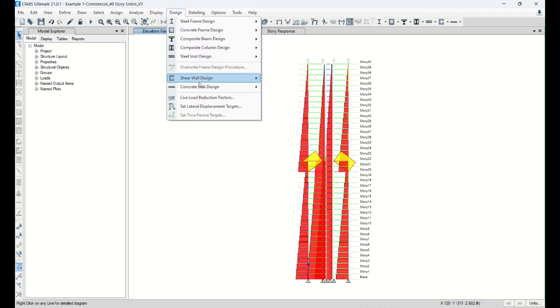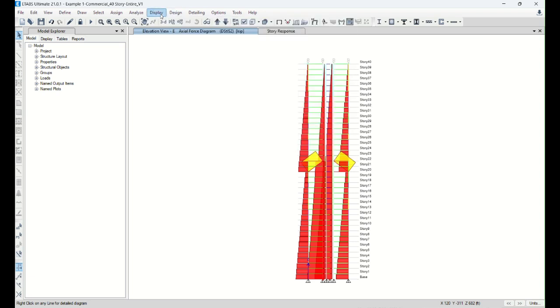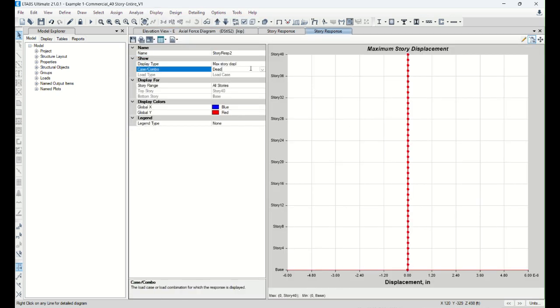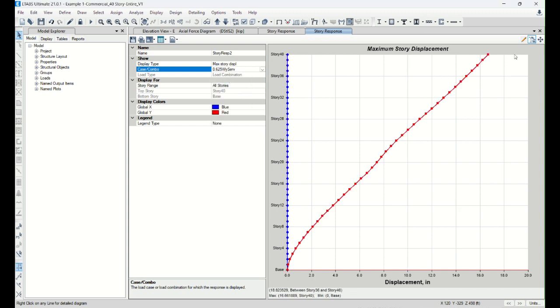I may have to create a few more example slides, but here is the displacement plot. Let's check how much this outrigger contributes in the Wind Y service wind load. So you initially had 21 inches, now it went down to 16 inches, right? So basically this outrigger is tying the column and working together with our wall. So we gain some lateral stiffness, so that the overall deflection reduced from 21 to about 17 or 16 inches.